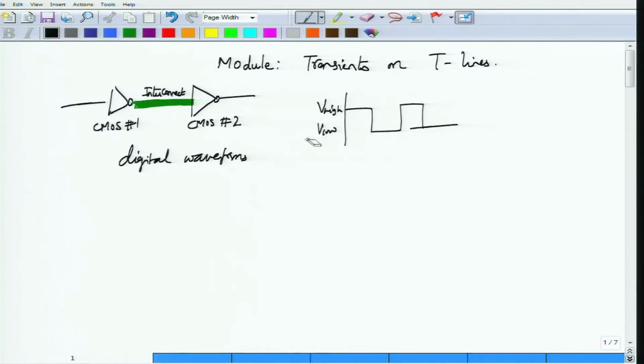In the case of a TTL circuit, these highs and lows have certain values, and in the case of CMOS there are different values for V high and V low. Regardless of all that, there would be this switching. If, for example, this is considered to be a clock, then this output should continuously be switching compared to the input. Okay, one more inverter is actually required, but that's another point.